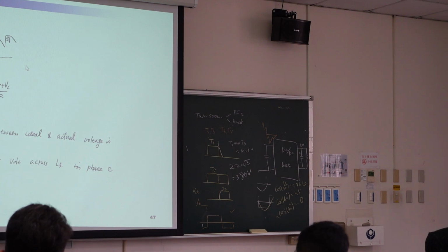Then what happened? The voltage changed quickly. Then it creates a lot of EMI to influence your facility. If you use a computer near this circuit, then your computer doesn't work because of dv/dt, the voltage changing quickly.